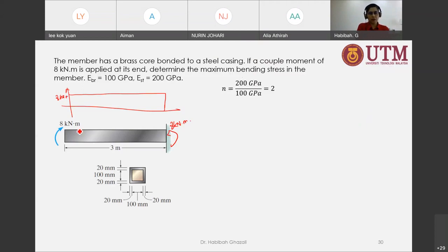In the kitchen, the clock is above, the counter is below. So when our point load diagram is going clockwise, in our bending moment, it should go up. Okay, the clock is up. So it's going to go up and it's not going to experience any other concentrated moment. There's no distributed load. So what's going to happen? It's going to go constant. And this is going to go back to 0 because we have this reaction force. So that's exactly what we did just then. So that's why I did not show this.